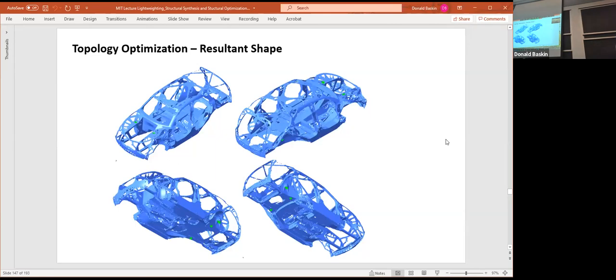So we at Mercedes developed this tool called the soft kill option that mimics that. We put together a car body, and then we apply these different stresses like I've shown you here. And then we calculate, with a finite element analysis, where the stress is the highest. Then we start adding more metal where the stress is highest and take it away from places where the stress was low.